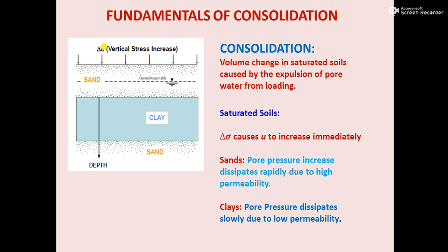However, in case of sand, what will happen? Because sand has high permeability, as soon as the stress increase happens in sand, water will take up the pressure, and because of the high permeability it will go away from the sand, and immediately the pressure will be transmitted to the sand, and that's how the sand will settle immediately. That's called immediate settlement. We'll come to that later. Now when the clay has low permeability and does not allow the water to move away very fast, the water will first take up the pressure. If you go to the next slide, you will understand it very clearly.